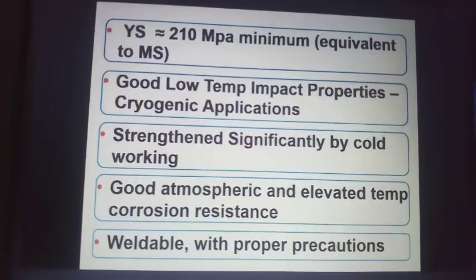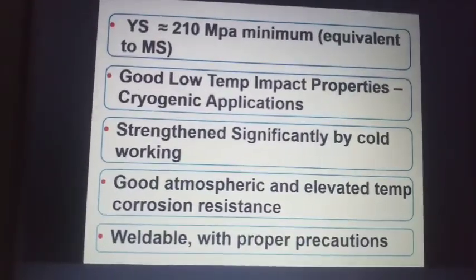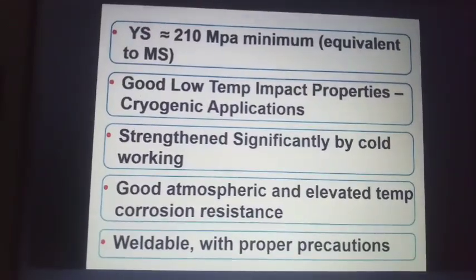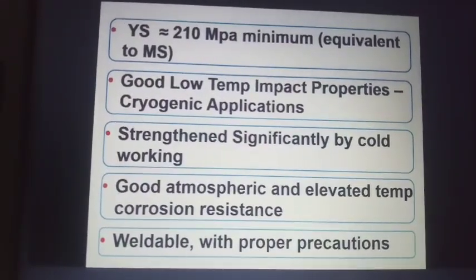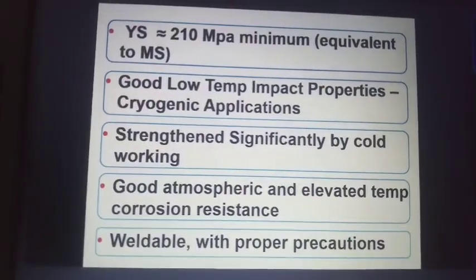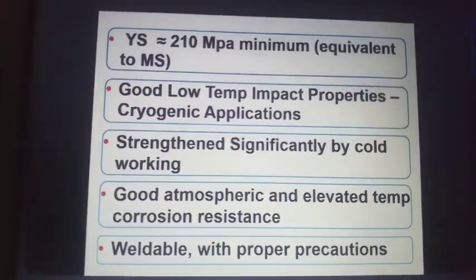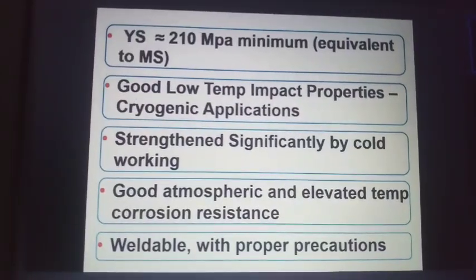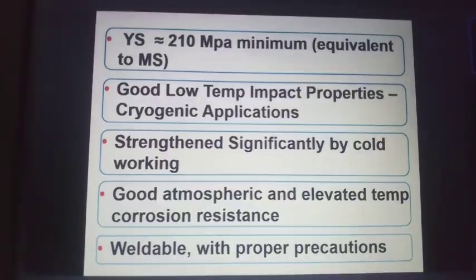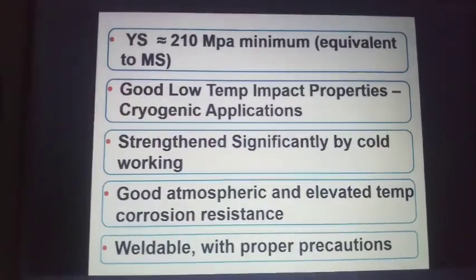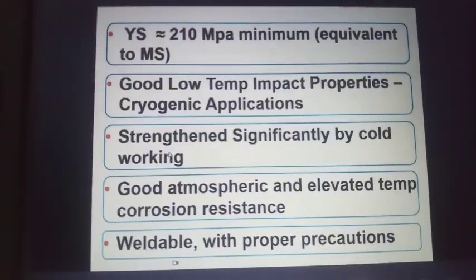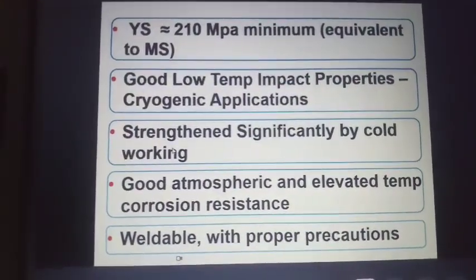We can exempt, but for duplex stainless steel, if it's more than 10 mm, we need to mandatorily do the impact testing. There are some minor exceptions. But apart from that, generally to guarantee a ferritic material at low temperature, we always need testing, because if there is a ferrite phase, we cannot trust that phase, it is not trustworthy. So austenitic means good toughness property.